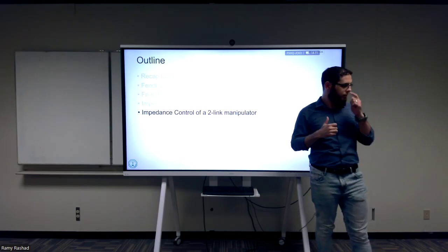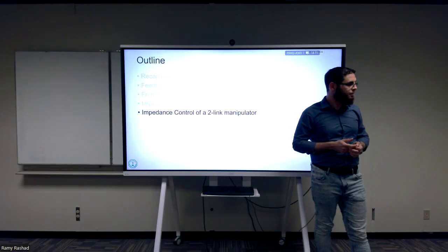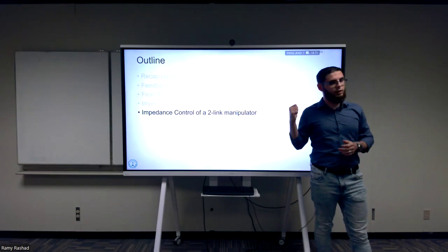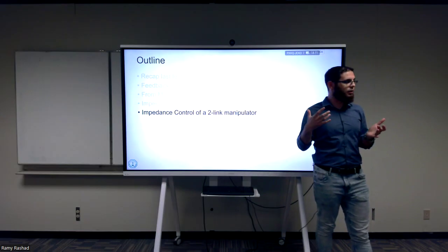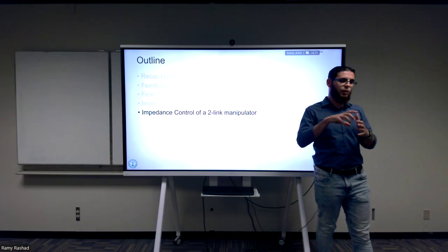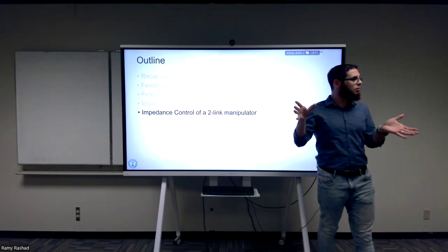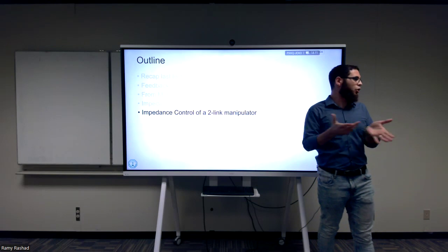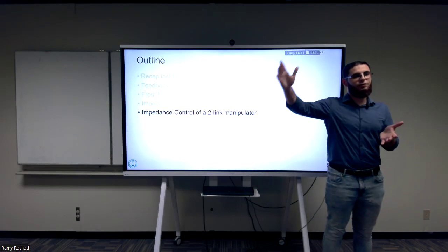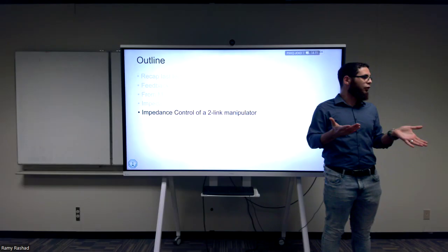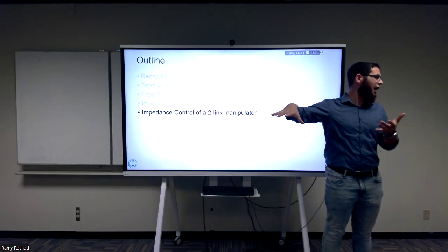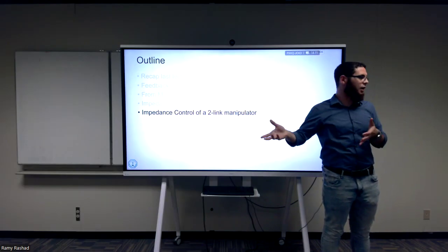That means that we can actually do impedance control without having interactions. But the interaction sense that we're thinking about here is interaction with an environment that you want to affect. Gravity, we always want to cancel it because we don't want the robot to just fall down. We want to compensate for gravity, and then we have a gravity-free robot. Then we start thinking of the control.